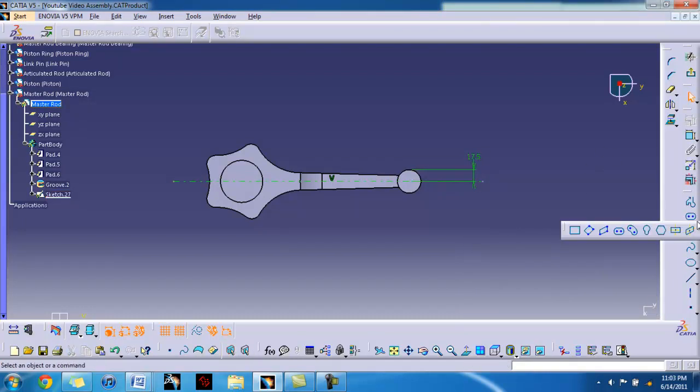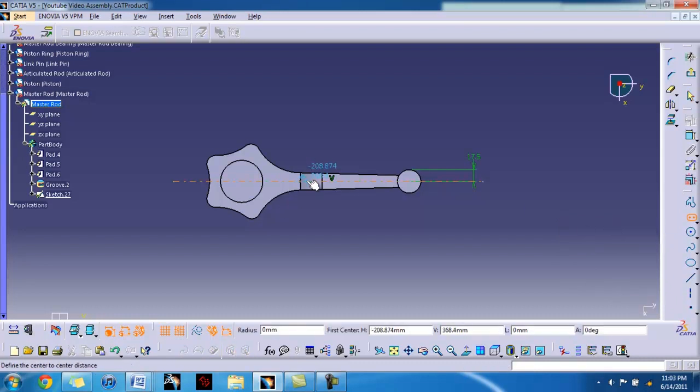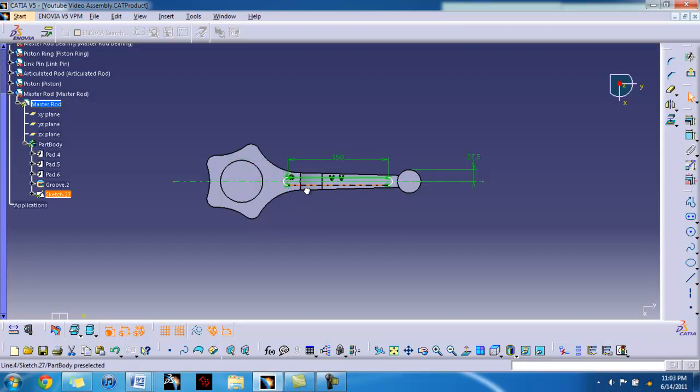Alright, so the elongated tool can be found under the rectangle command. Click on that. On the axis, make sure you click right on there. We want radius of 6 and a length of 150. And you want it to be horizontal or vertical, so make sure it's blue. Now even though it's on this axis, you can still move it from side to side.